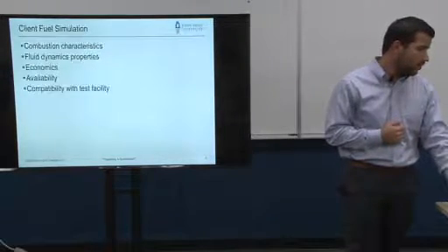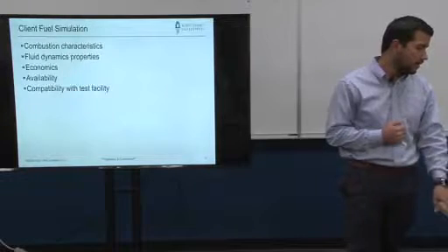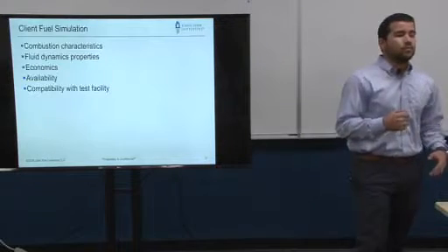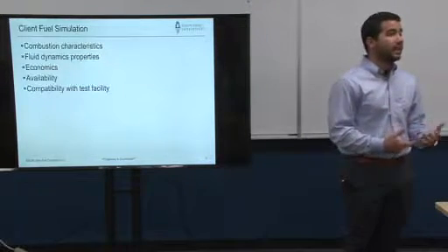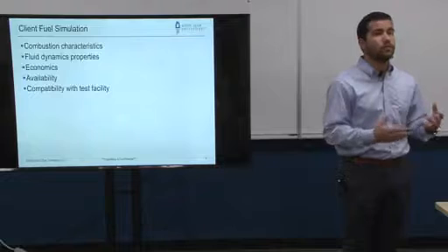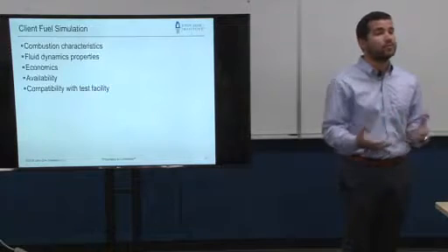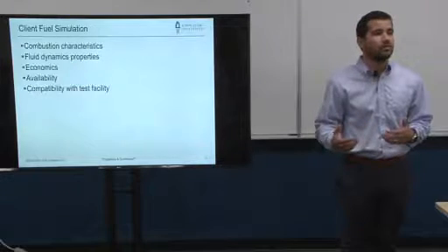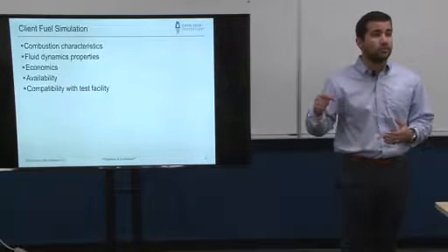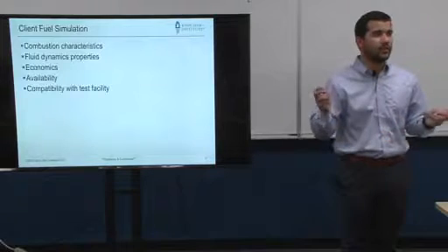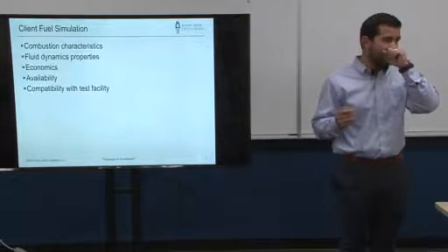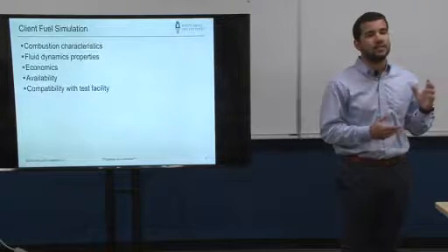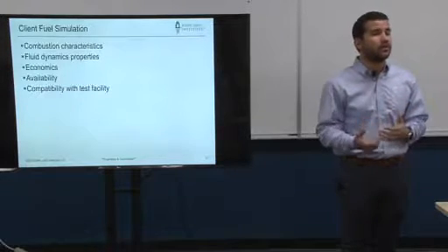So let's talk about how we look at fuel simulation. Depending on where you are located in the country, you will have different fuel compositions, and even depending on the processes that you're running. A lot of refineries tend to use byproducts of their process as fuel, sort of like free fuel, right? So a big part of our testing is making sure our burners are stable with that particular fuel.